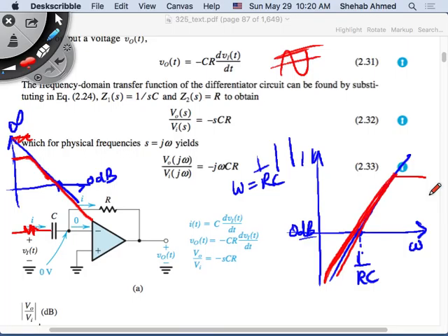But the bad thing is that anytime you have reasonably high frequency content, I'm amplifying it too much. So anytime you have a signal like a square wave, a square wave includes steps, which are impulse functions. These impulse functions have infinitely high frequency. So what's going to happen to this frequency content? It will always be amplified. Even if, for example, you have a ramp that rises very fast, right?